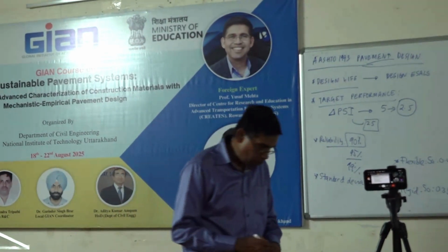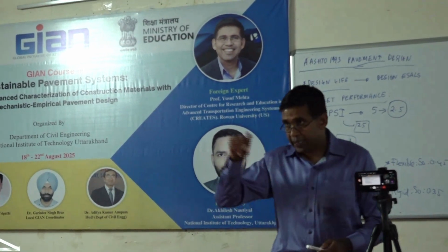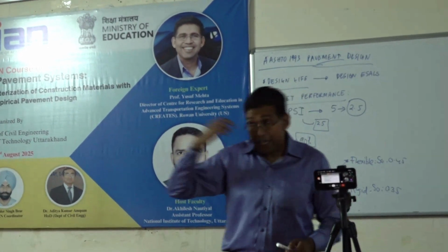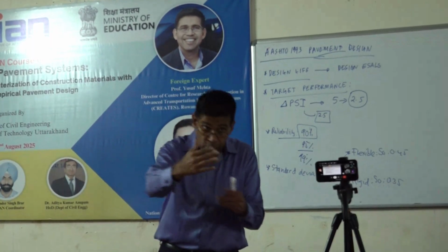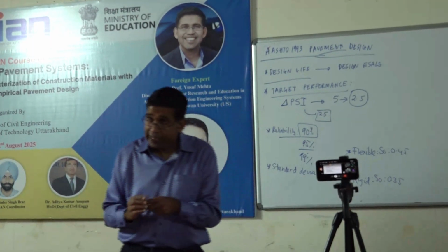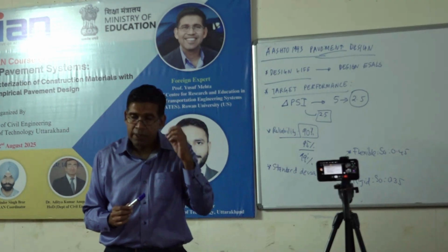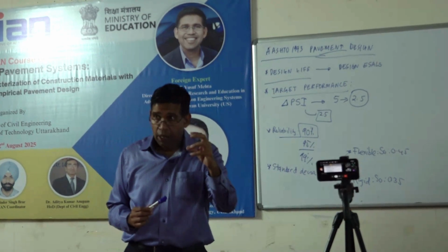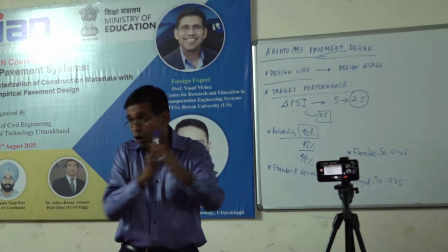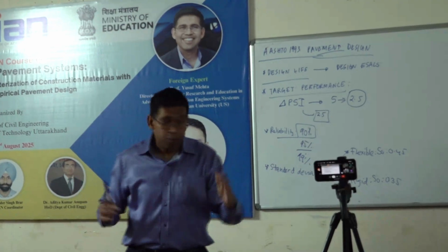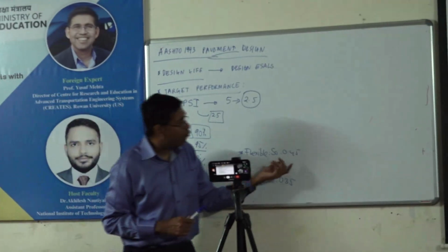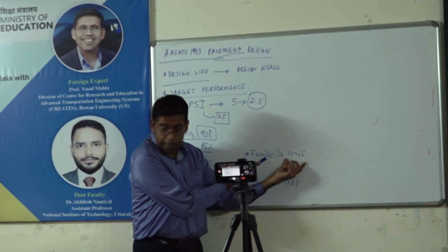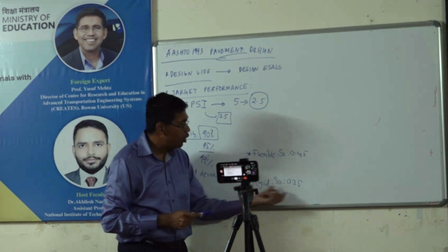When the AASHTO design was done, remember that yesterday I gave the explanation of the 10 sections, right? So there was variability in the mixes, there was variability in the soil, all of that stuff. What they did was, they gave an aggregate number, one single number, looking at the standard deviation of all the properties, if that makes sense. Okay, so it was a very strategic way that for those sections, whatever that number was, for flexible pavement, asphalt, it was 0.45. For rigid, it was 0.35.